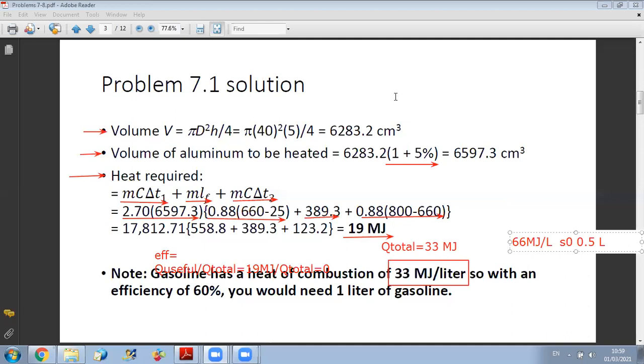In case you have a mixture, you have solid plus liquid, then the heat provided will not lead to an increase in temperature, but will lead to an increase in, if you want, the energy of the molecules, which will allow them to change from state to state. So whenever I have a mixture, I don't have an increase in temperature, but I have a change in state. And when I have a complete change in state from 100% solid to 100% liquid, this means that I have absorbed the total amount of fusion heat, which is provided also in joule per unit mass.